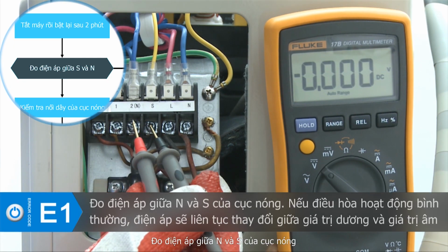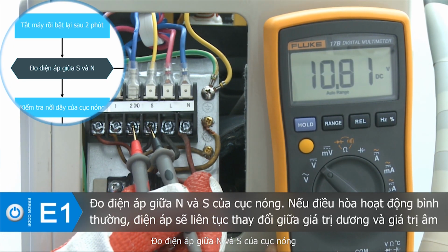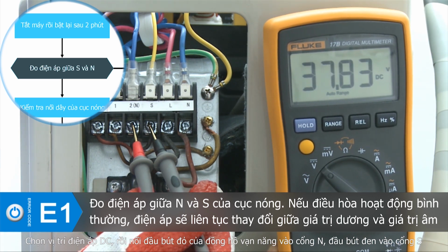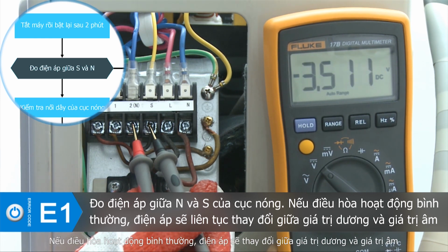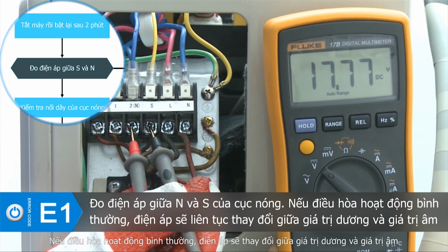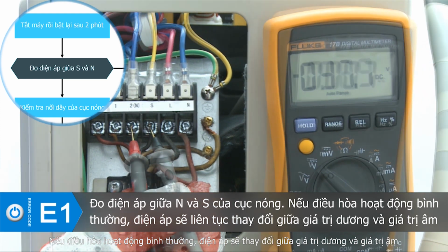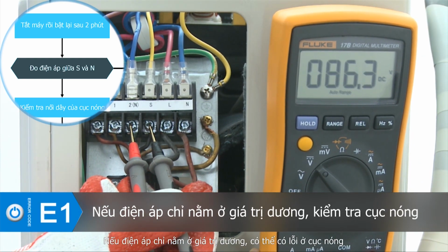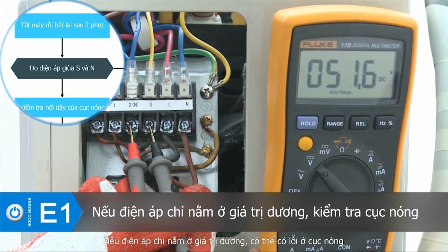Measure the voltage between N and S of outdoor unit. Select voltage DC position, then connect the red pin of multimeter to N ports, the black pin to S port. If the AC is operating normally, the voltage is moving alternately as positive values and negative values. If the voltage has always been the positive value, possible malfunction may be occurred on the outdoor unit.